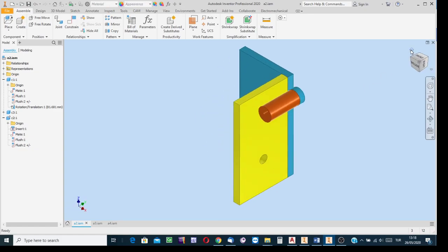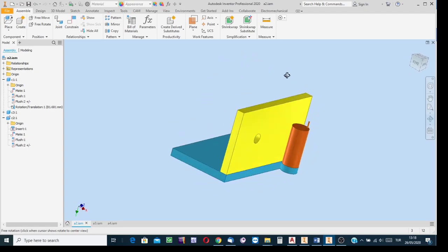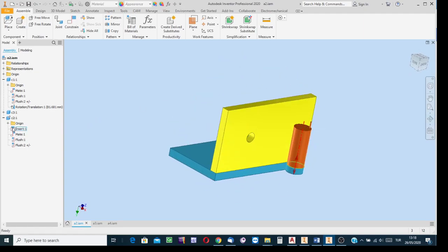How about the other constraint? When I drop this list, well, I found for component 2 another constraint symbol, insertion type, but in the constraining list for component 1, there is no such icon. This means the insertion type constraint has been input not to relate component 2 with respect to component 1, but with respect to another. Well, there is one more component you see. It is the brownish one, component 3.